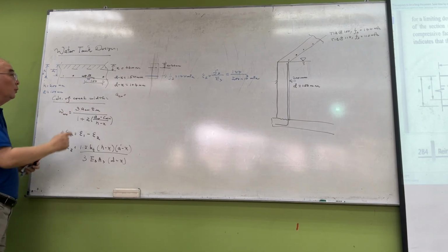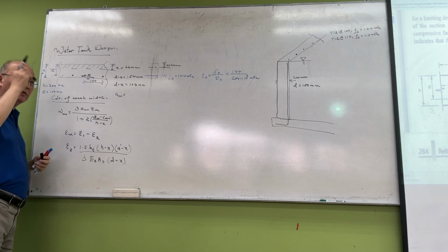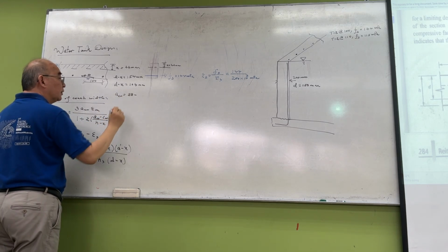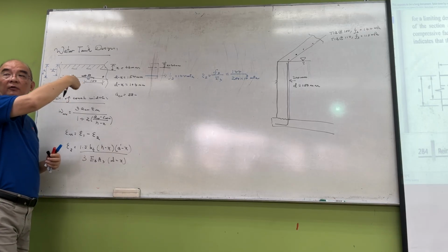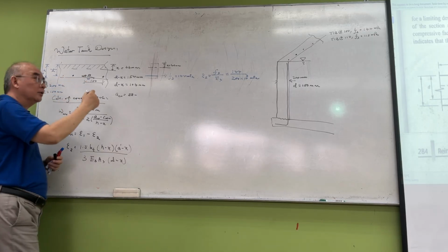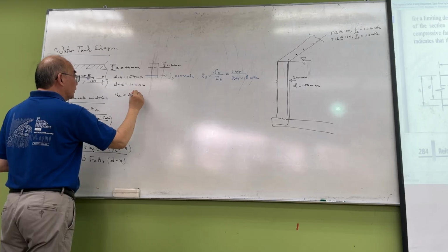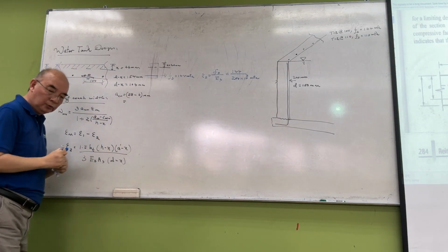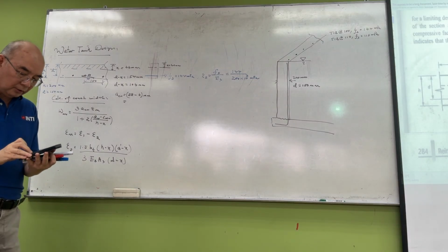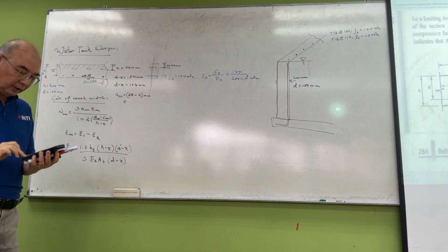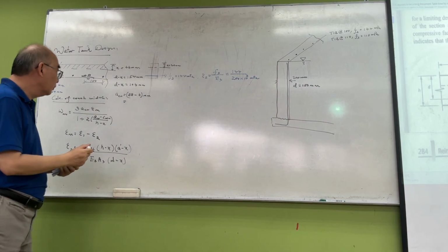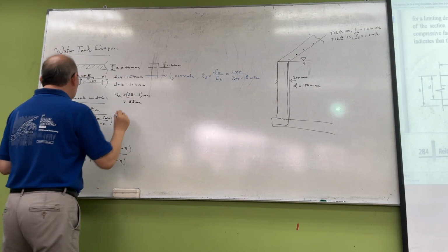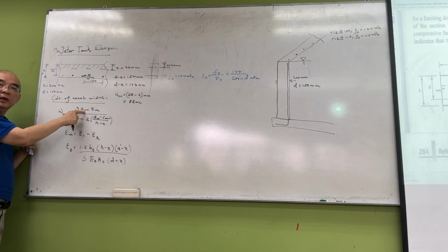You want it to be the surface of the rebar, so it should be 88 minus the half of the diameter, which is the radius, which is 6. So 88 minus 6 is 82. So A crack is 82. We already calculated A crack.